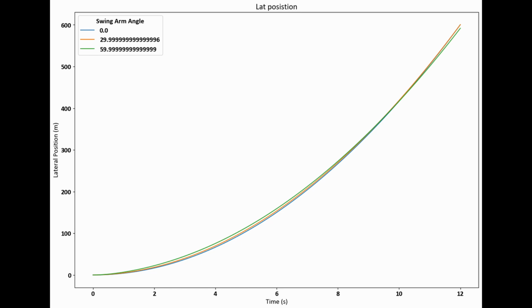If there's enough time, let's say, the horizontal suspension linkage is going to surpass the suspension linkage with an angle and its jacking force. But if you're in a tight course, like let's say autocross, you may benefit from having jacking force, because you'll gain acceleration faster, but know that you'll have a lower overall steady state value for lateral acceleration. And I'll show you some data to have you think about that.